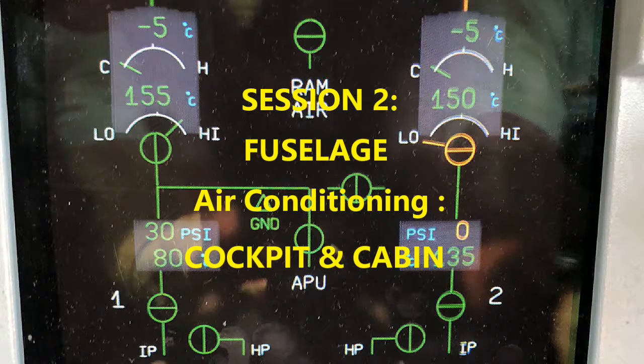And so these fans are operated electrically, okay, and those are going to be supplying air into those areas. But that air flows into the lavatories through the grills in the door and into the galleys, the same way. And the extraction fan is extracting, so it's going to be removing air from the lavatories and the galleys through a duct, which is installed above the cabin ceiling. Okay, all that is just going to go through a valve overboard.